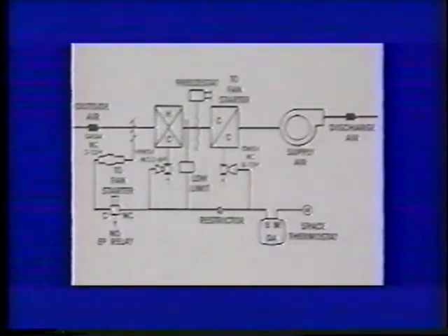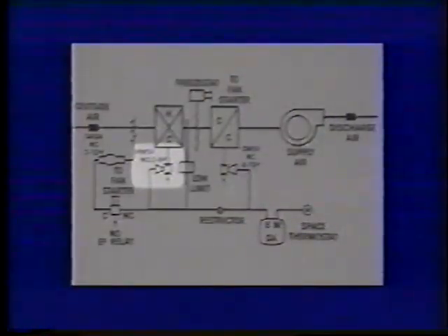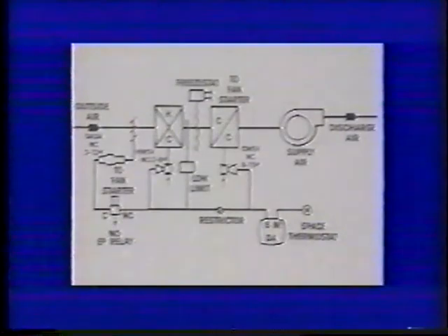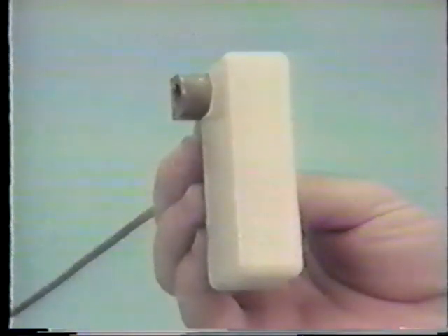In the event the airstream temperature controller senses a decreasing mixed air temperature approaching the set point, it will begin to bleed off branch line air, allowing the normally open hot water supply valve to open independently of the space thermostat signal. This allows the system to react to a drop in mixed air temperature before the space thermostat has to react to a drop in space temperature. The 2260 controller is shipped with factory settings of 20 degrees Fahrenheit throttling range and 60 degree Fahrenheit set point.